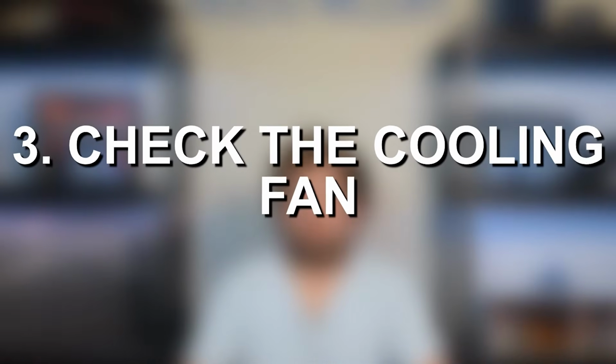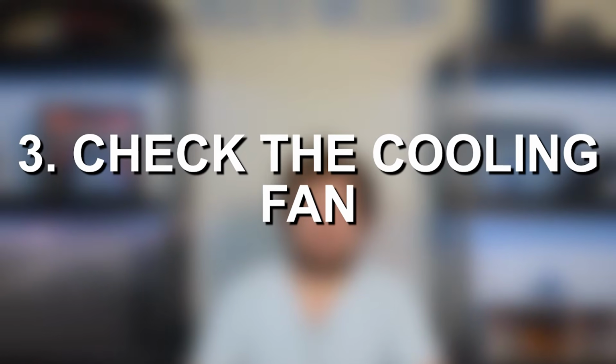After that, try to confirm whether or not the cooling fan is actually kicking on. Most vehicles, especially on a hotter day, if you're idling or stuck in rush hour traffic, you will actually hear the electric cooling fan running, and it can generally be pretty loud, especially when stopped or idling for an extended period. So you can check that, see if the cooling fan is actually turning on.